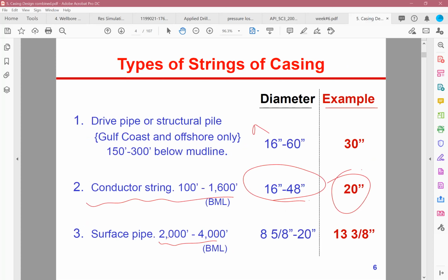So if you remember, basically they talked about their setting depth casing, and one of the reasons that they set the surface pipe here in this area is that they have those coal mines underground that are depleted, and they actually took out those formations, and there might be like 20 feet or 30 feet of height where there is nothing there.